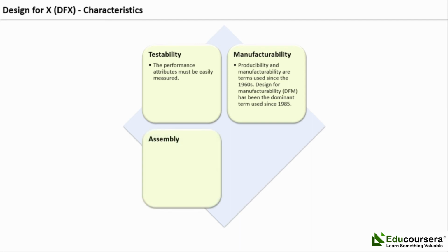Assembly. Design for assembly, DFA. DFA means simplifying the product so fewer parts are involved, making the product easier to assemble. This portion of DFX can often provide the most significant benefit. A product designed for ease of assembly can reduce service, improve recycling, reduce repair times, and ensure faster time to market. This is accomplished by using fewer parts, reducing engineering documents, lowering inventory levels, reducing inspections, minimizing setups, minimizing material handling, etc.